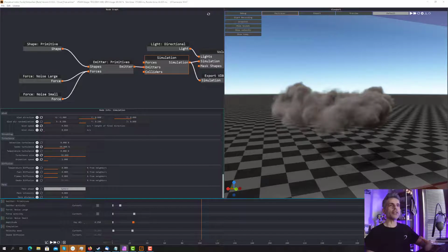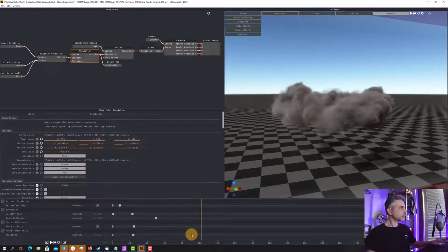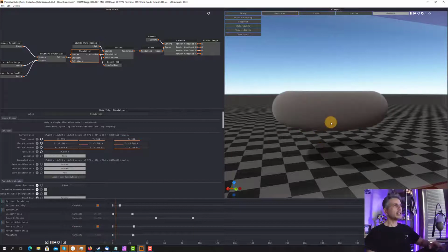So we can animate, and let's go to create some keys. We'll have a key for a high diffusion of 35 until frame around 50, and then maybe we'll have something lower. Sorry, I have to, let's double check. Okay, that's my fault. Okay, and let's go here for maybe 0. So we have high diffusion at the beginning, and then it is going lower and lower.